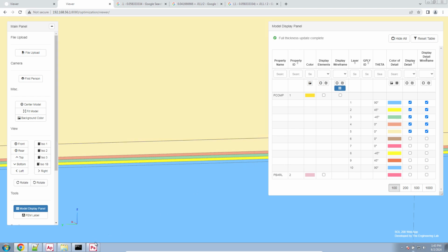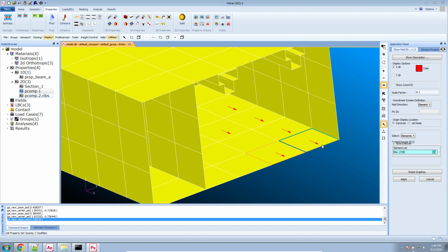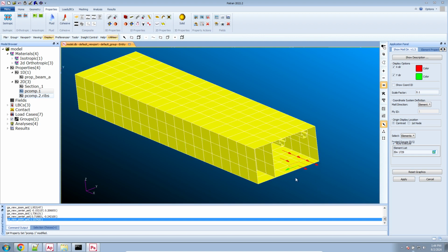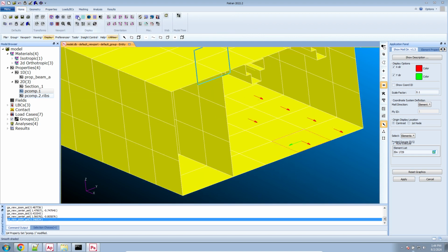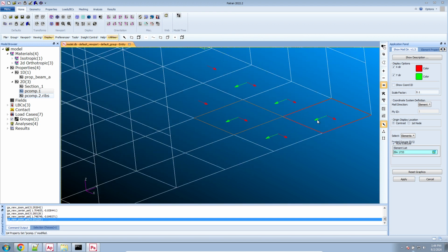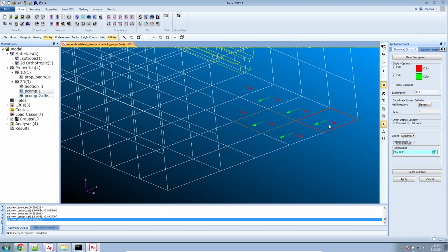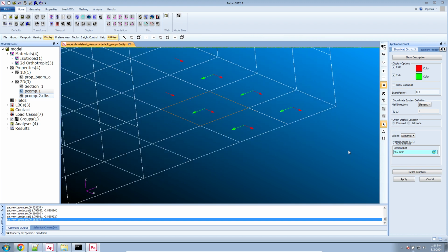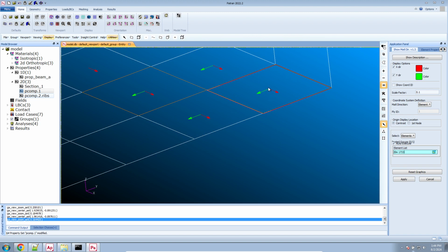in this case. Now here, if you look in Patran, this is how you can determine the stack and sequence order. Turn on the Y direction checkbox and click apply. And let's go ahead and select the wireframe and click these. If you use the cross product of the X and the green axes, this is going to tell you the Z axis, if you will. The Z axis is the direction of your stacking sequence. Here, if you do the cross product, there's a blue arrow, if you will, that goes in this direction. So layer 1 would be here on the top, and then layer 2, 3, 4, 5, and 6.